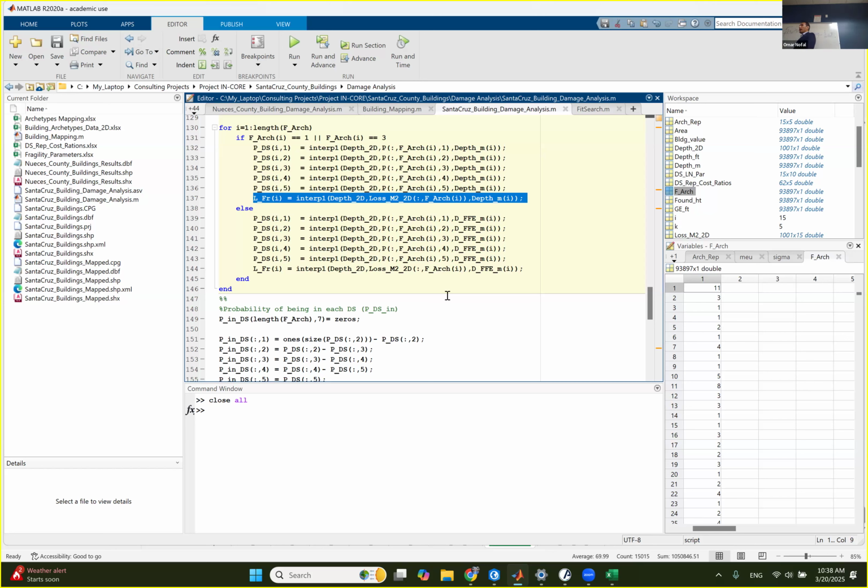I want to calculate all these values, and the maximum value of these is going to be the maximum probable damage state. So this is no damage. Let's say no damage. This is going to be damage state 1, damage state 2, damage state 3, and this is damage state 4. So the maximum probable damage is 40% to damage state 2. So at the end of the day, we're going to say that this building has the highest probability to be damage state 2, because this is the maximum probable damage state. All right. So that's what I'm trying to do now.